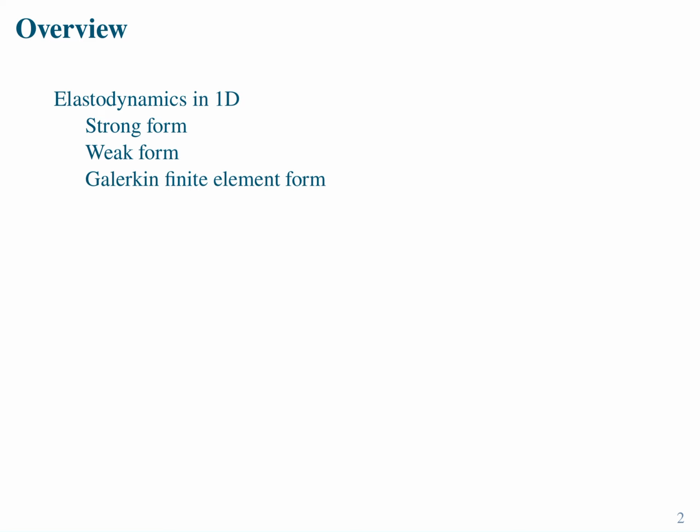And then that equation cannot be solved yet because we don't have infinite resources, right? So we need to discretize the equation to be able to do some number crunching in a computer. And so this is where we apply the so-called Galerkin projection to lead finally to the finite element discrete equations. And once we have them, we can finally solve them.